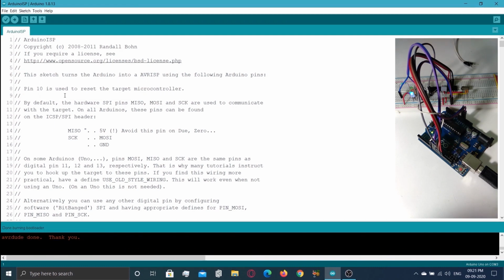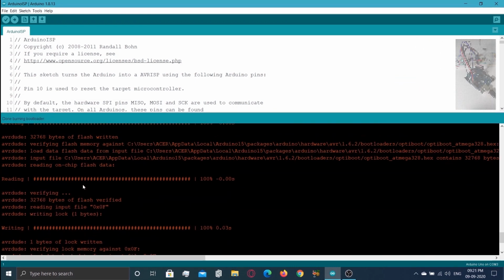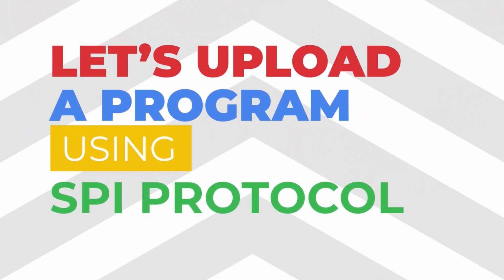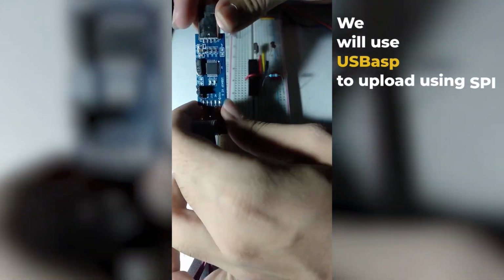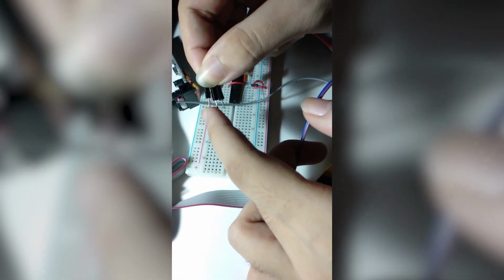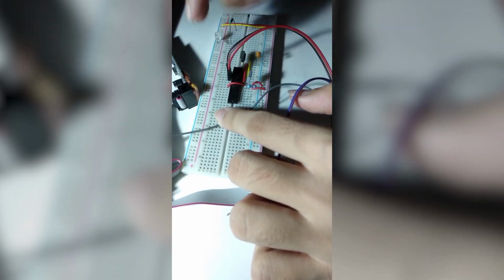Now that we have prepared the target microcontroller, we can program it using SPI and UART. But at first, we will upload the program using SPI. We can use the same Arduino as ISP board as programmer, connecting the MOSI, MISO, SCK, reset, VCC and ground pins to the target to program it. Or we can use special programmers like USBasp, which is very inexpensive and widely available, and it's open source. The connections are almost the same for both Arduino as ISP and USBasp. However, a schematic explaining the connections can be found in the description below, as always.